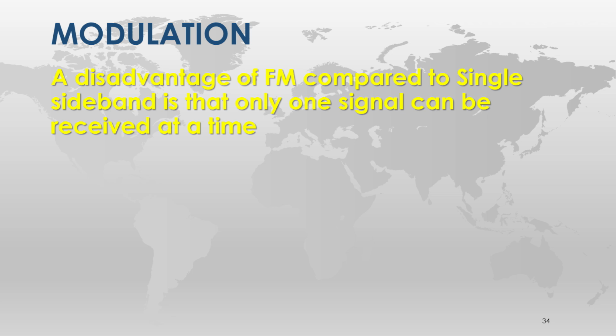They could, but we have a convention that on certain bands we use lower sideband, and on other bands we use upper sideband. You're not required to, but that's the convention. If you're scrolling along and you hear a signal and you can't make heads or tails out of it, try the other sideband. Yes, you can have a conversation here and a conversation here, and that's why sideband gives us more opportunity to get more signals into a given amount of bandwidth.